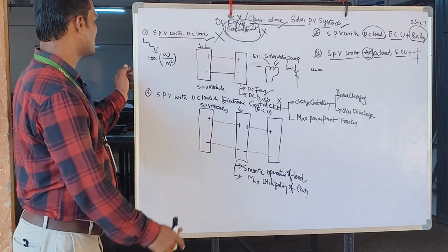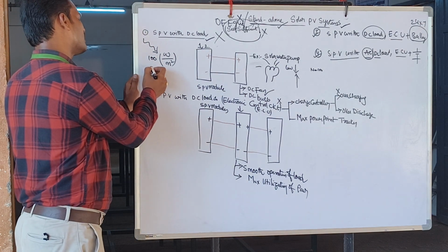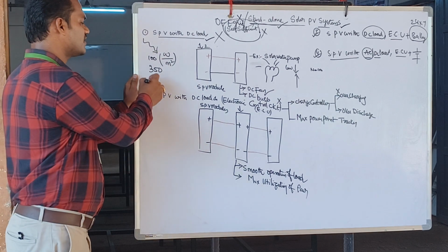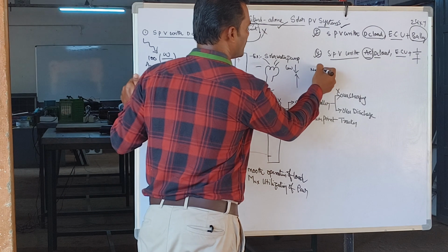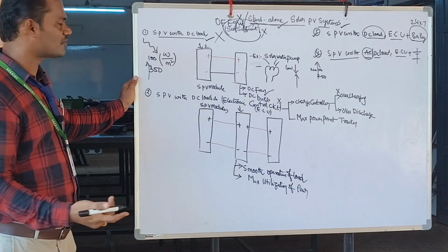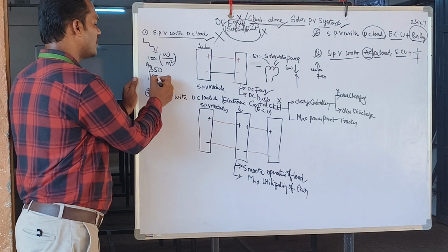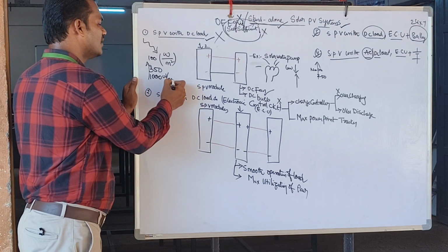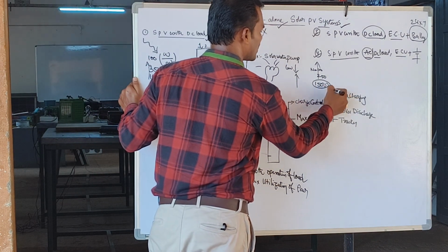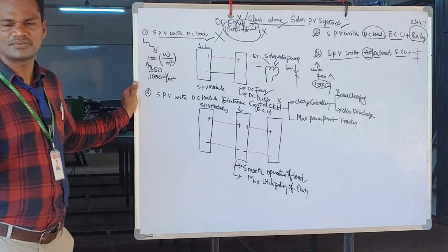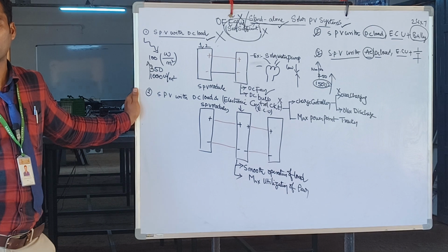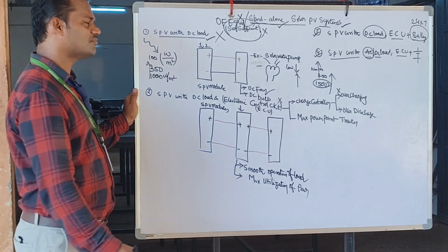Then, for example, at 10 o'clock, the irradiation may be around 350. So irradiation is increased, and automatically the fan speed may increase to around 250 rpm. Then you may be satisfied. But at 1 o'clock, it may reach the maximum, which is 1000 watt per meter square, and the fan speed will go up to 1500 to 1600 rpm. The fan will try to rotate at maximum speed, which is not desirable for us, and you can have discomfort.